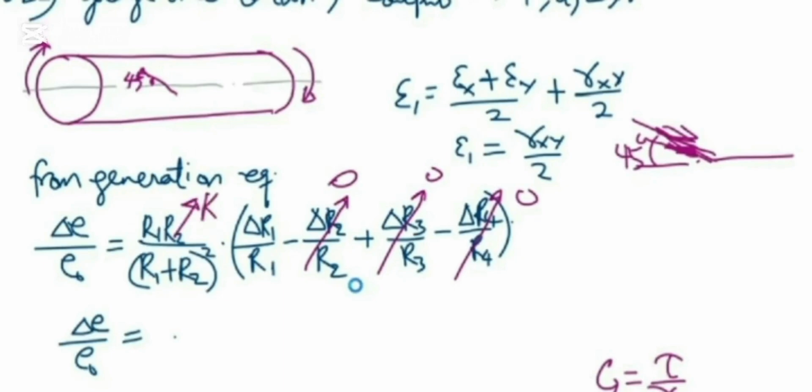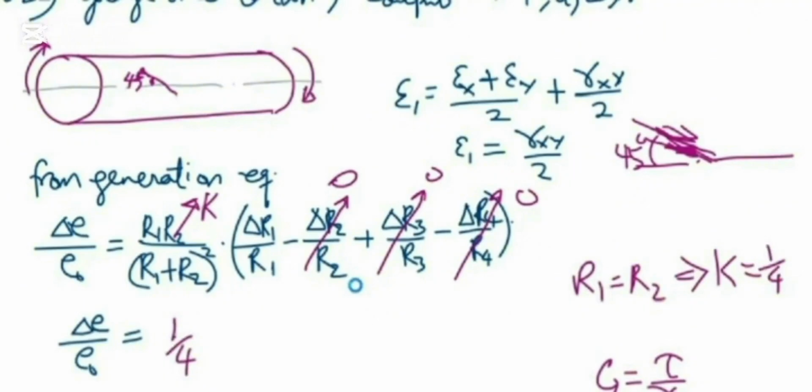In this case, the circuit is a Wheatstone Bridge. So at maximum circuit sensitivity, R1 is equal to R2, which implies circuit sensitivity K is equal to 1/4, which you can also prove, isn't it? So it's going to be 1 over 4 multiplied by the change in R1 over R1. In this case, our change in R1 over R1 is the same thing as S_A E, right? S_A E1, it doesn't matter, where E1 is equal to what?